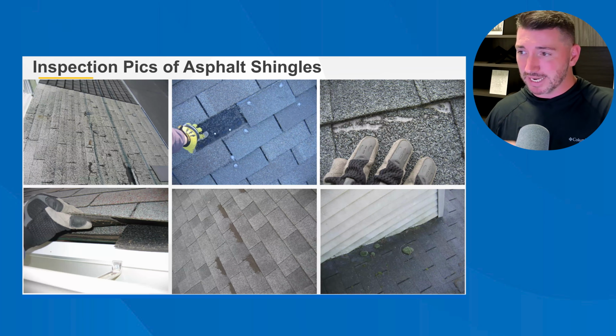And you can see the ones next to them are probably a nice fiberglass base mat. They're newer anyway. I think it's a Certainteed Hatteras, which is actually a discontinued shingle, but this is an old picture. So you're seeing those organic shingles. The base mat gets waterlogged. It starts to break up and fall apart.